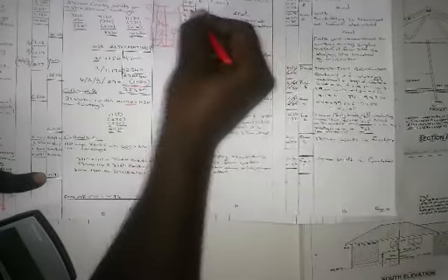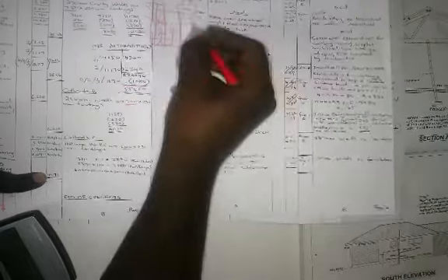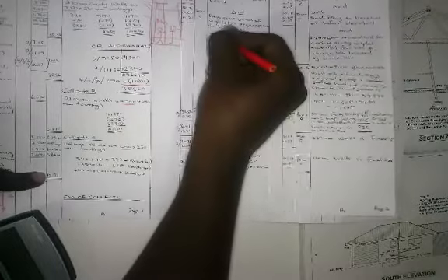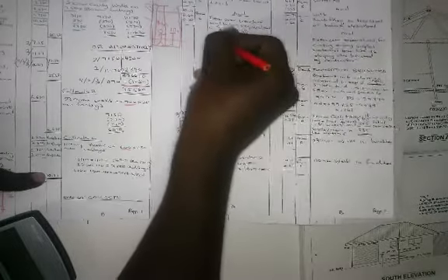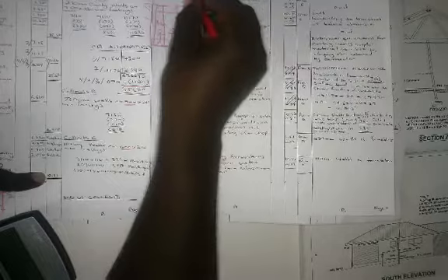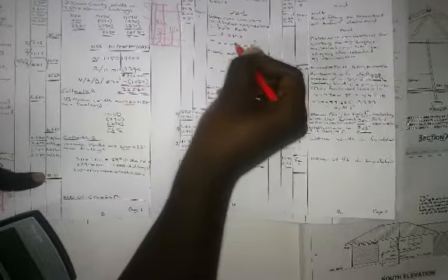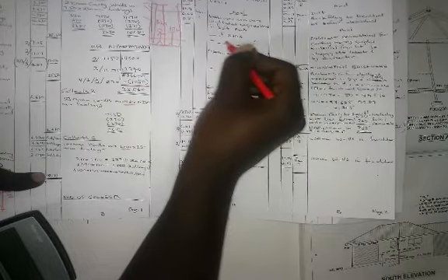Then you go to your 110 wall. You take your center line as specified and take your width, which is 600. That's 10.71 times 0.6 times 0.8. That's your depth. And all these cubes apply to also here.